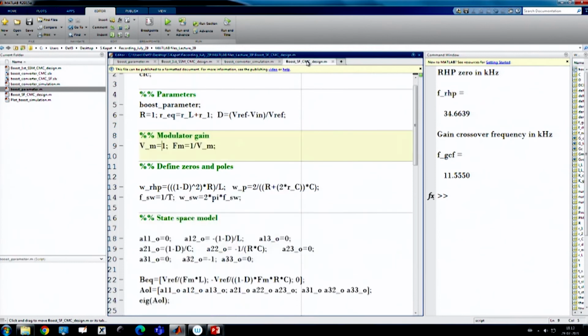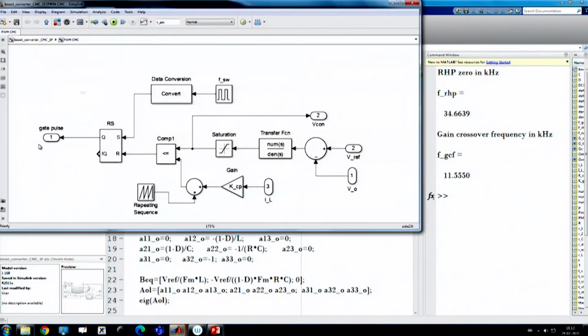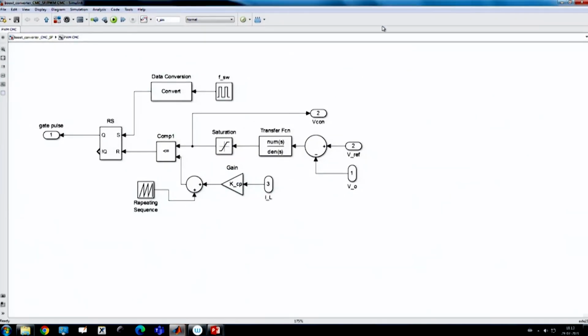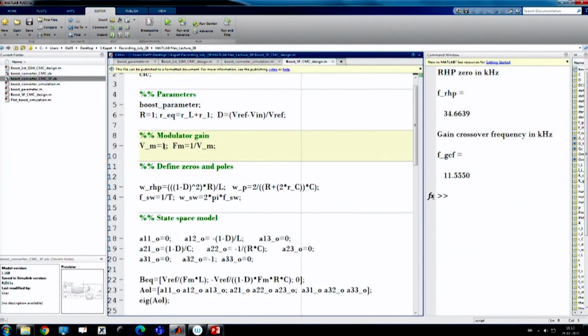Now, I am going to the state feedback based design, and if you go to the state feedback based design, in the control everything is the same, only I am adding a gain with the current loop, and since I told that there has to be a compensating ramp, because it will work like a modulator, I am taking a very low ramp, it is just 1 volt, because your input voltage is very low, it is not very high, 0 to 1 volt.